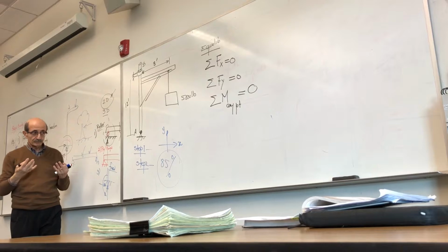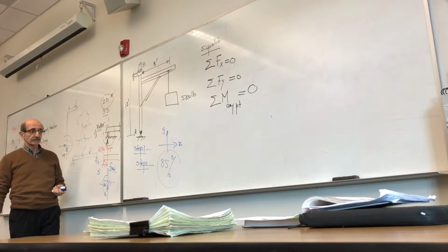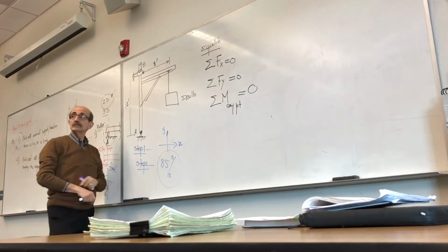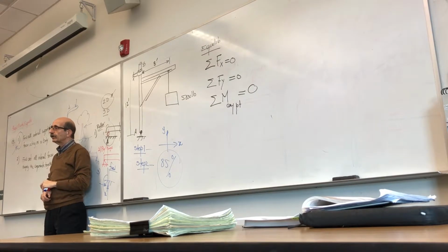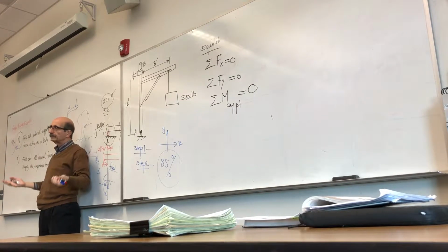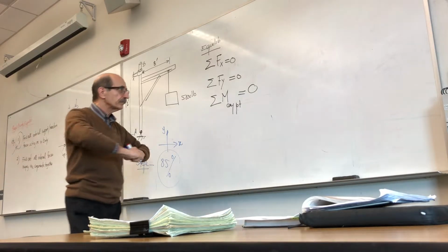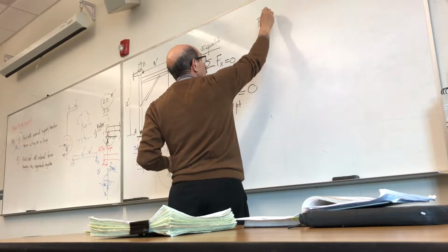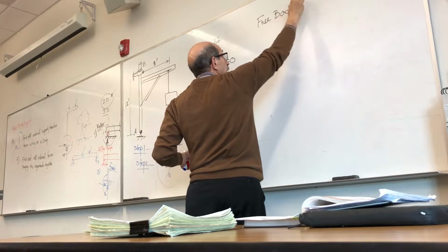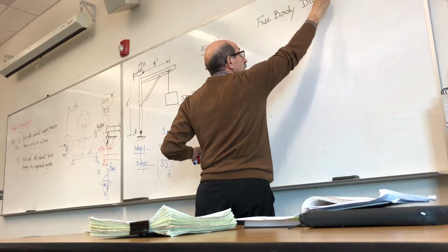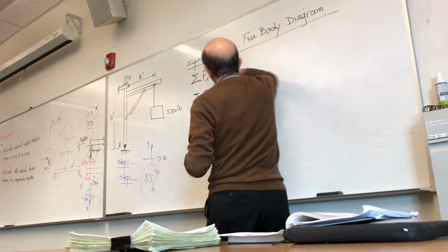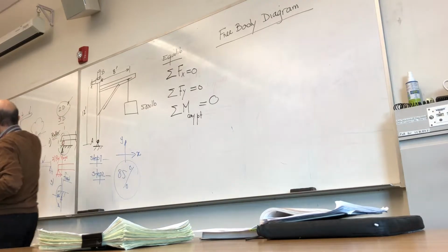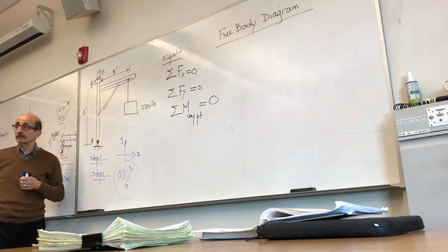The platform, the interface, is this. You need to convert this structure, its support, applied loads, to a set of forces and moments. How do you do that? Through setting up what we call free body diagram. Free body diagram is what allows you to apply these equations of equilibrium and find the unknown forces externally acting on the structure, which is the first objective of rigid body equilibrium.